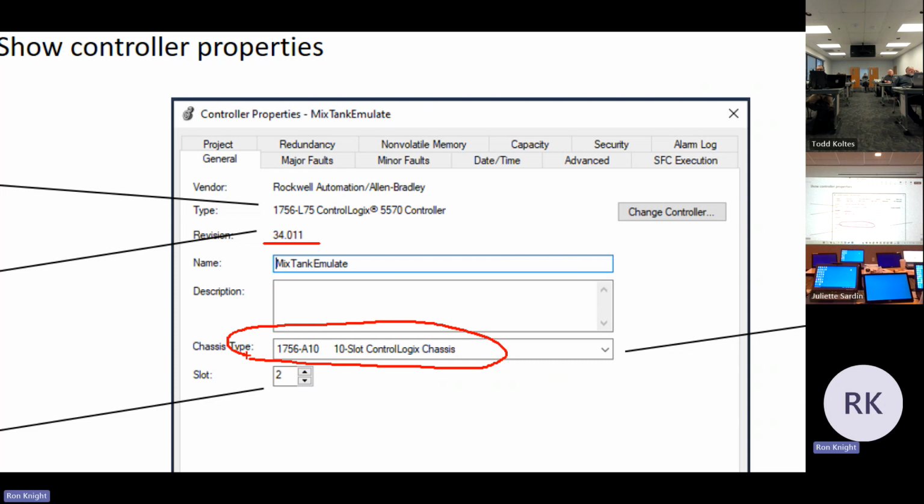The modules mount on a rail, and the PLC is always the module furthest to the left, other than any power supplies. And you can't have multiple PLCs per rail. Now, we can exchange data between PLCs at I/O rates, very high speed, but they're not going to be sitting on the same rail.